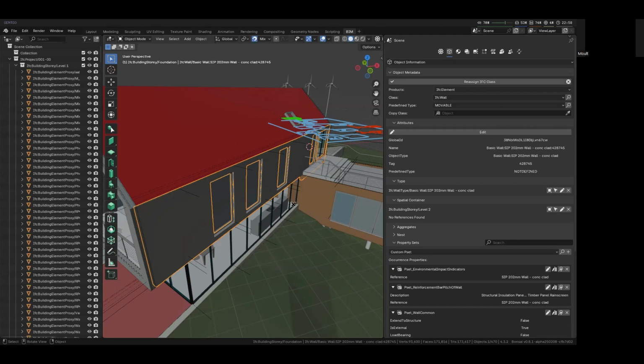Or also quantity takeoff. The type of IFC object determines the type of quantities that are automatically calculated by your software or have standardized measurement methods on them. Whereas these external classification systems, like Uniclass, are standalone. They're just a hierarchy of object types, but they don't integrate very well into other systems.